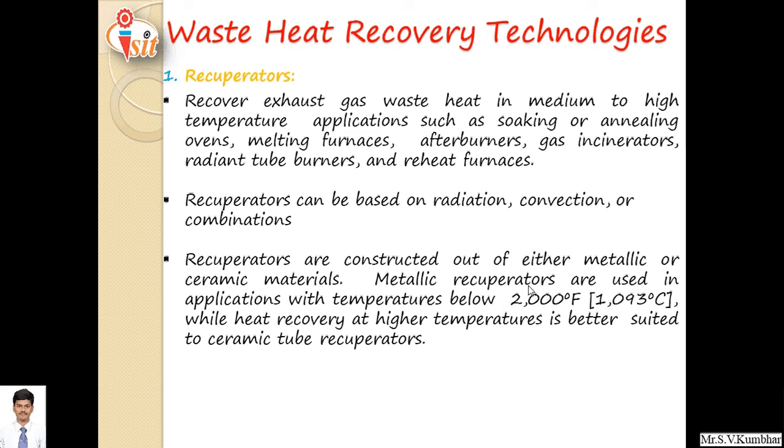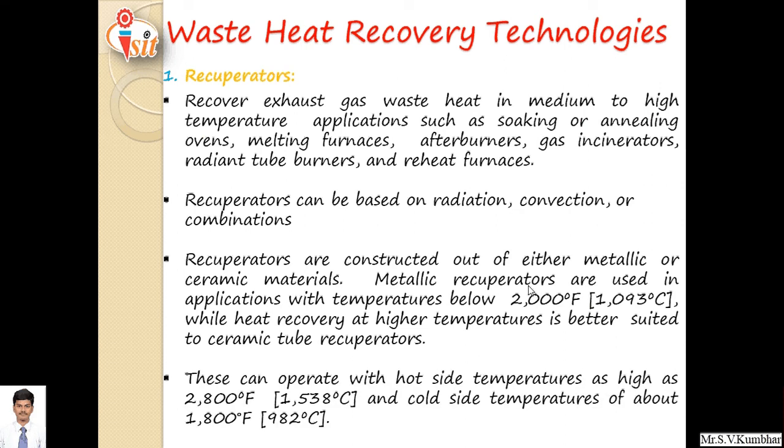Generally, recuperators are constructed out of either metallic or ceramic material. Metallic recuperators are used in applications with temperatures below 2000 degrees Fahrenheit, that is 1093 degrees centigrade, while heat recovery at higher temperatures is better suited to the ceramic tube recuperator, which can operate at a high side temperature as high as 1538 degrees centigrade and a cold side of up to 982 degrees centigrade.